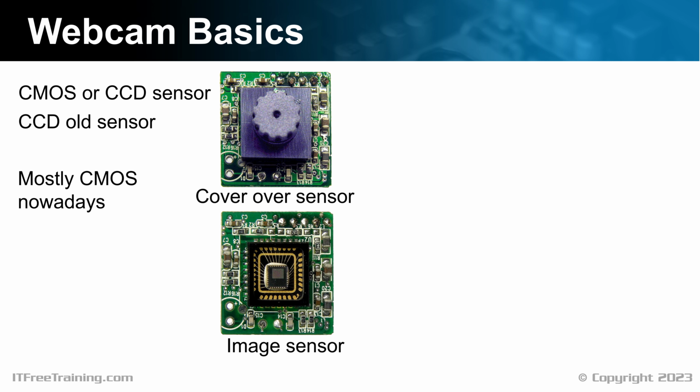To get an idea what kind of quality you can expect, the sensor will determine the resolution and quality the webcam supports. Looking at the resolution can be a little misleading. It is not uncommon, it actually happens more often than not, that the sensor will measure less resolution than the maximum supported resolution. To get the higher resolutions, the electronics in the device will use averaging and other upscaling techniques.